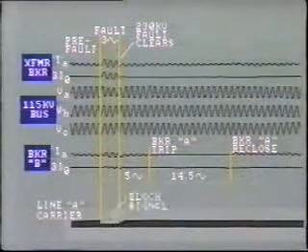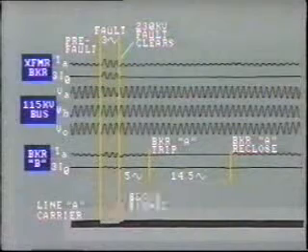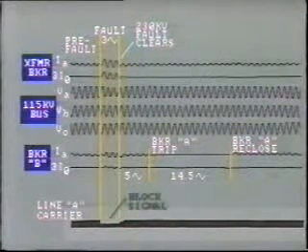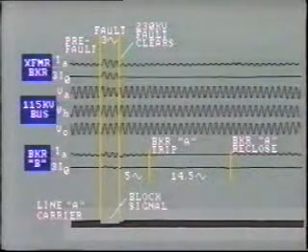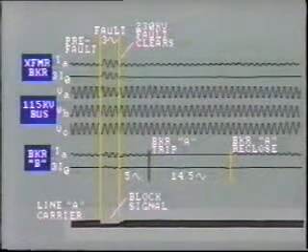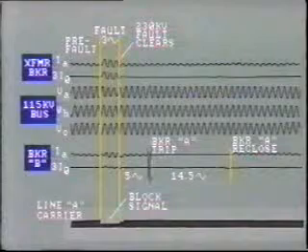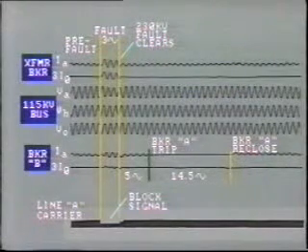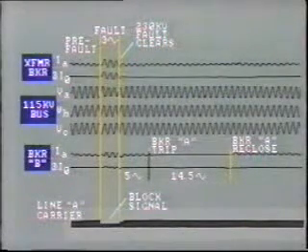Further investigation revealed that while the fault was on, breaker A received the proper carrier blocking signal. But this signal was removed too quickly. As a result, the relays at breaker A saw fault current as well as a green light to trip. The problem was solved by resetting the timing of the carrier block signals. Again, this is a case where the over-trip problem may have gone unnoticed if we had not checked the oscillograms.